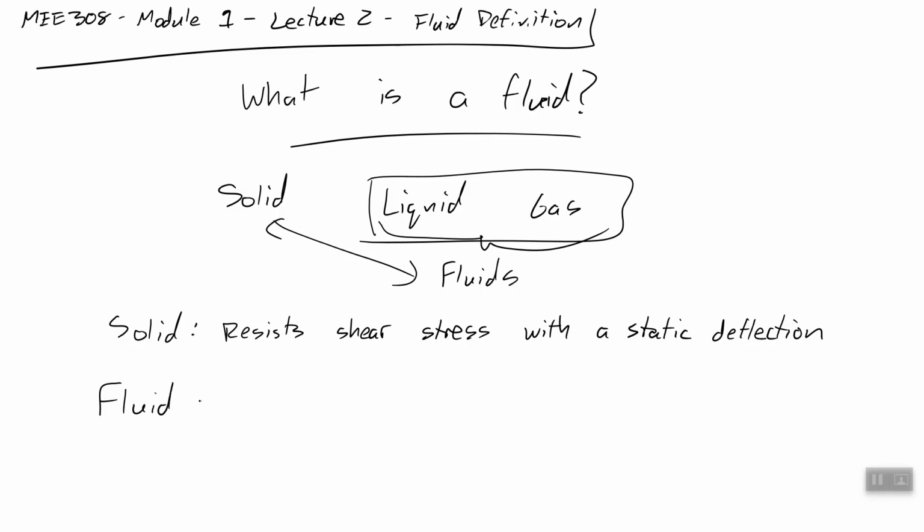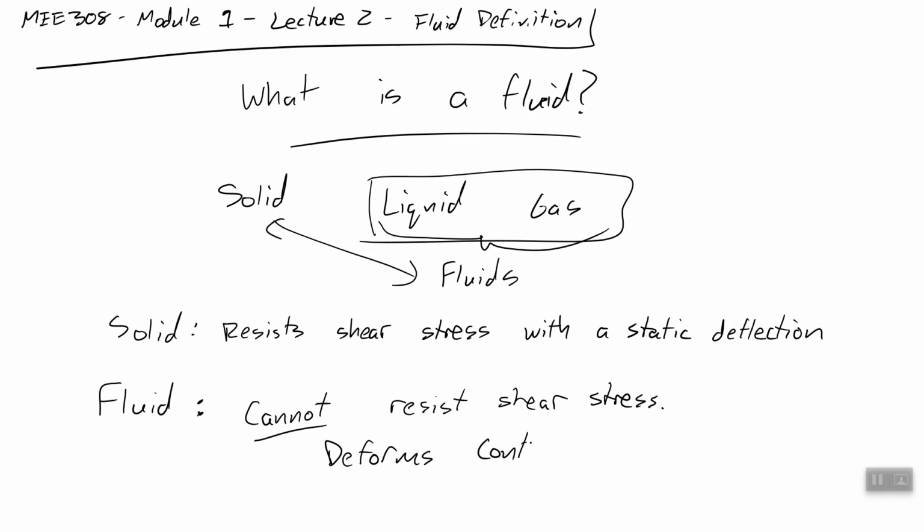A fluid, however, does not do this. A fluid, the most fundamental definition is that a fluid cannot resist a shear stress. Just can't resist, which means that when a shear stress is applied to a fluid, it deforms continuously. Where our solid, let's draw this out.